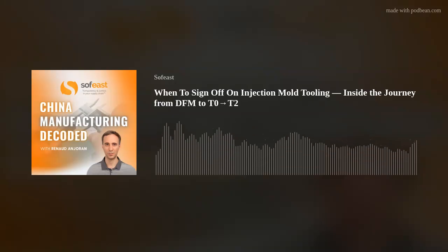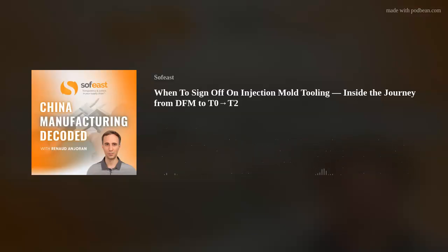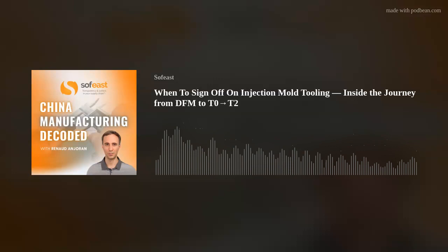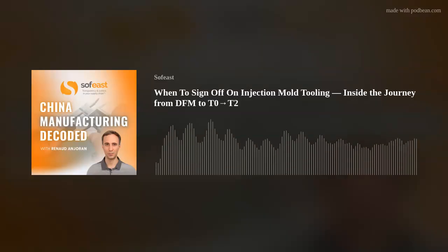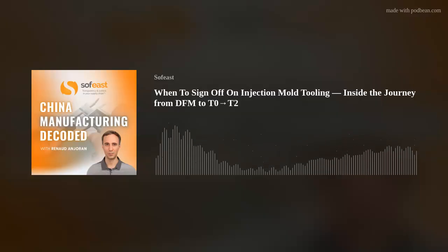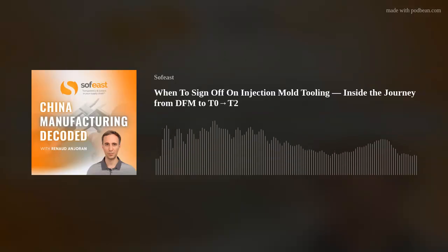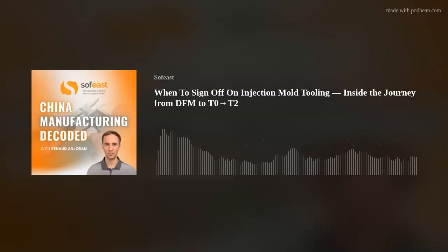The next part is the fun part. As an engineer, this is where we can start to make stuff. We've purchased all of the steel and all of the other components. As long as the steel is coming in, the other parts can come along, because we can do things in parallel during this stage. This is where we start the machining. I'm basically going to talk about the core and cavity for the moment. The bolster part is a whole different thing, but let's focus on the core and cavity, which is going to produce your actual molded part at the end of the day.